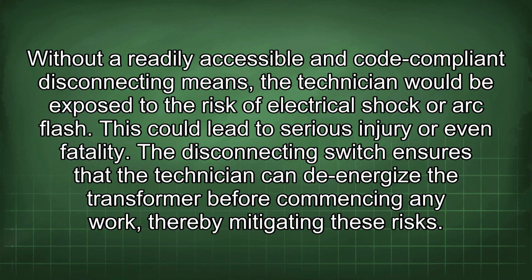Without a readily accessible and code-compliant disconnecting means, the technician would be exposed to the risk of electrical shock or arc flash. This could lead to serious injury or even fatality. The disconnecting switch ensures that the technician can de-energize the transformer before commencing any work, thereby mitigating these risks.